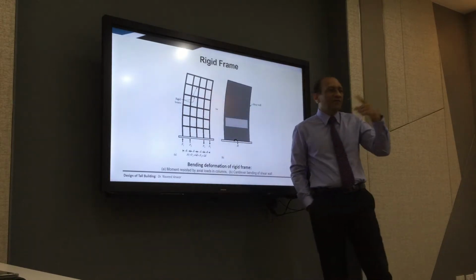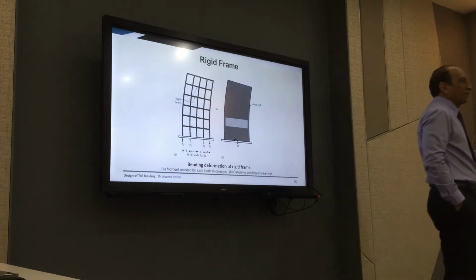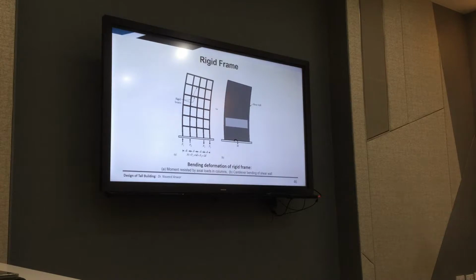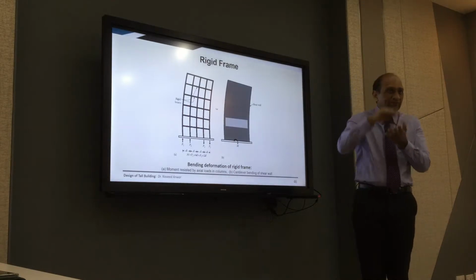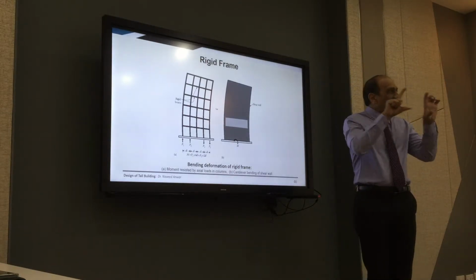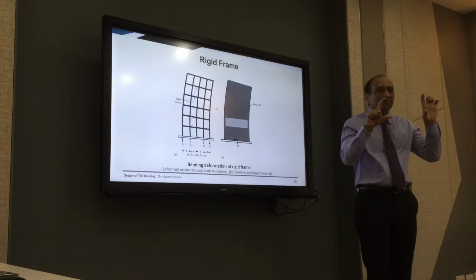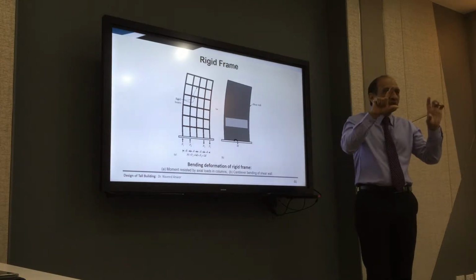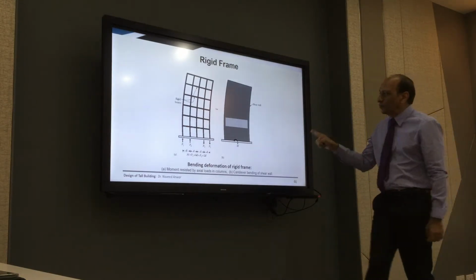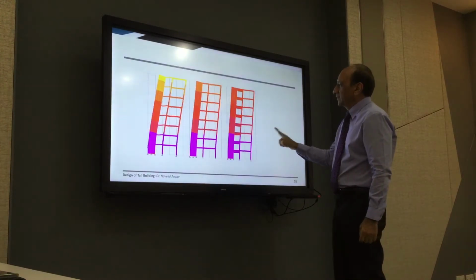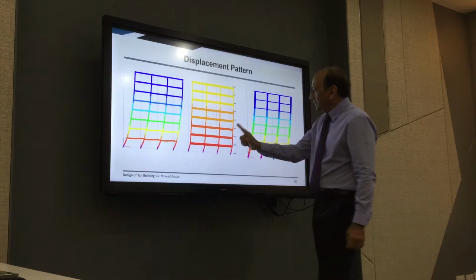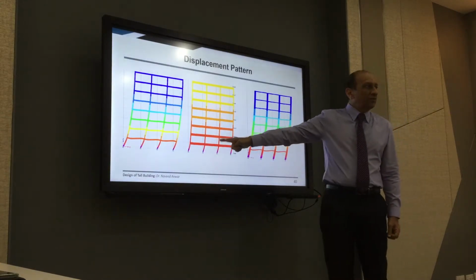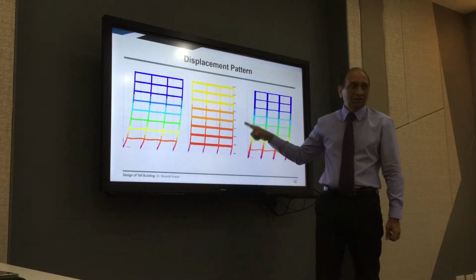So we can think of the column of the shear wall as made up of these fibers. These are called fibers. And these fibers are linked by very deep beams, 1 story high beams. So these beams have very large stiffness, so they don't deform. So if you go back to my previous slide, just imagine the same frame. Let's say this is a solid wall.